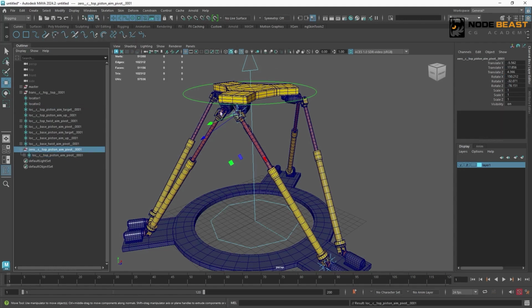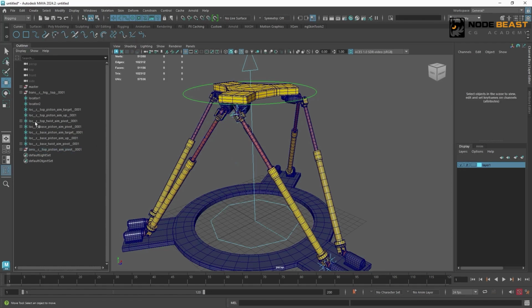Because the parent's coordinate system changed, in order for it to match the parent's coordinate system, it now goes back to its default values. This method is extremely common in rigging. For example, later we'll talk about creating controllers. To keep the controller's translate, rotate, and scale at their defaults, we'll do the same thing. Create a 0 group above it to change its coordinate position and the rotation. Okay, let's do the same thing for the other locators.